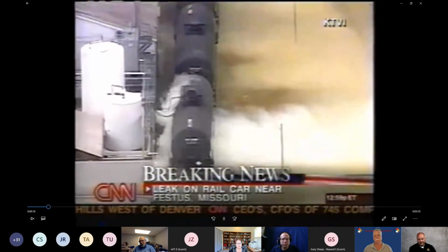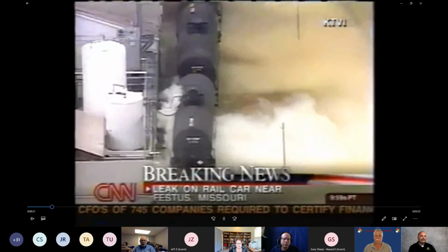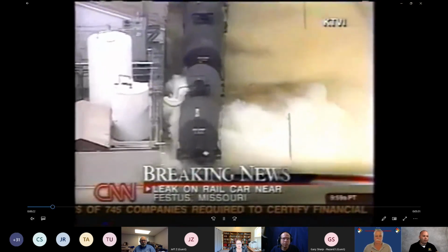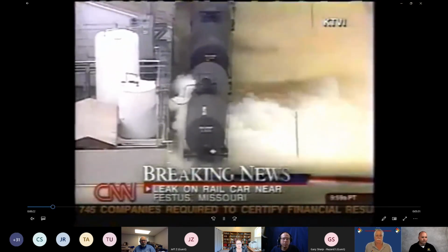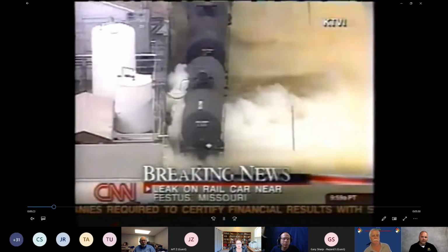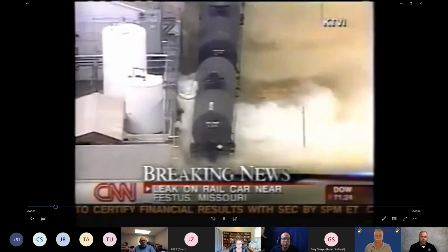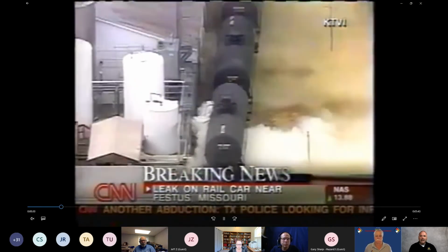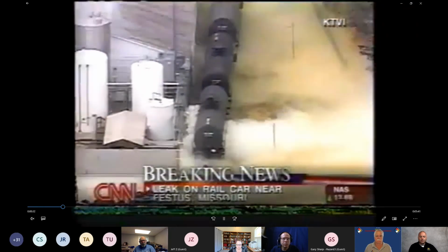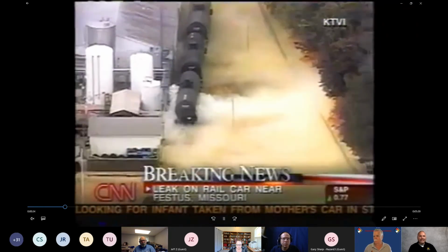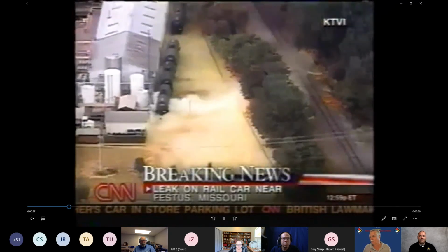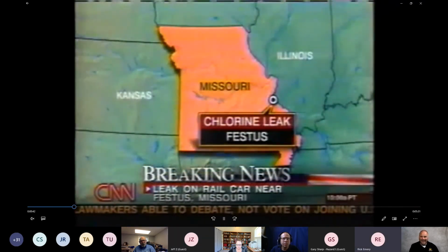They had an emergency system. What really happened was they installed the wrong hose. They would use these rail cars to fill up smaller containers for light industry or whatever it might be, and they installed the wrong hose. They put a stainless steel hose on where they were supposed to put a hose called Hastelloy. If I'm putting the emphasis on the wrong syllable, I don't know, but it was something like Hastelloy. And eventually the thing popped and broke.